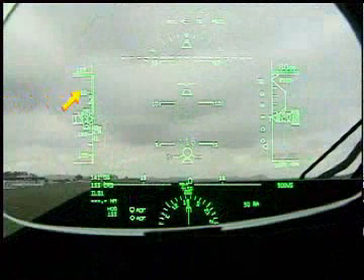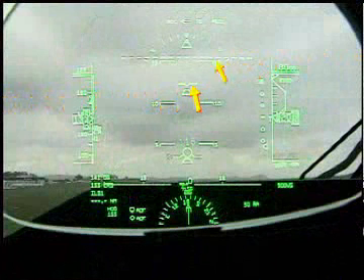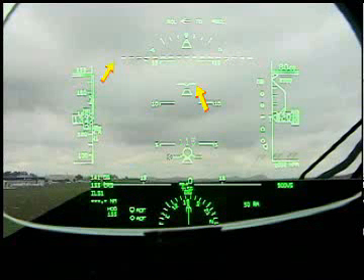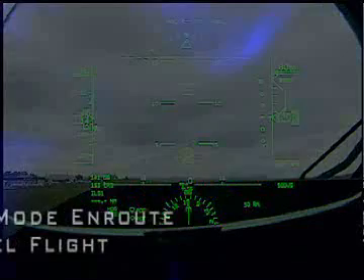In the video, the aircraft reference symbol is just below the takeoff go-around reference line, indicating that the pilot needs to pitch up slightly. Because of the pitch attitude, the HSI is pushed down partially. Observe radio altitude, the rate of climb, and the heading indications. The aircraft's acceleration is 0, indicated by the position of the flight path acceleration.